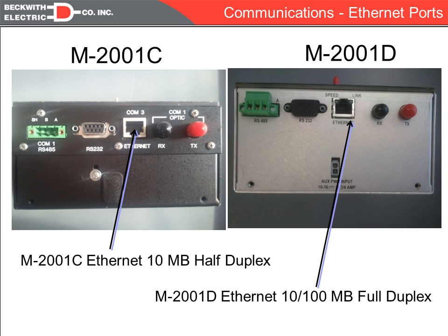Likewise, we can have the same options on the D. We show an Ethernet port on the C, but it actually is not a full Ethernet implementation; it is a terminal server. So it's actually a serial to Ethernet converter, which means that ultimate bandwidth is still 9600. You're still limited to one session and one protocol at a time because you're still interfacing ultimately with a serial port.